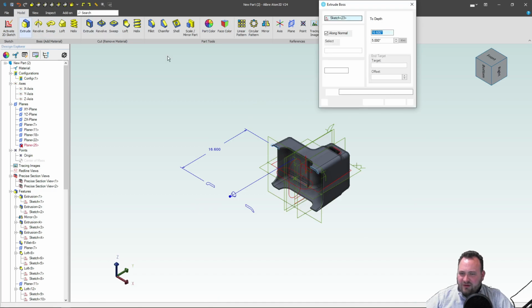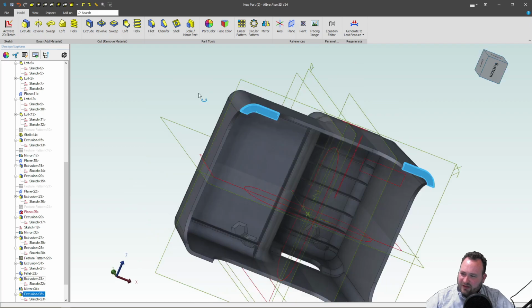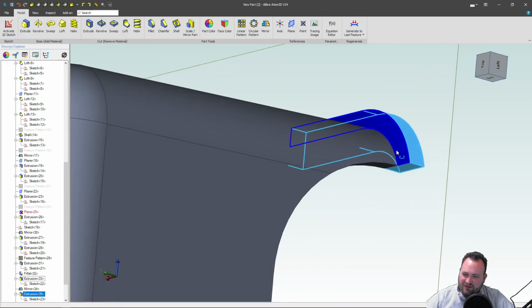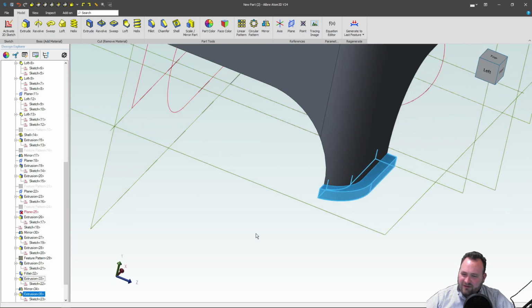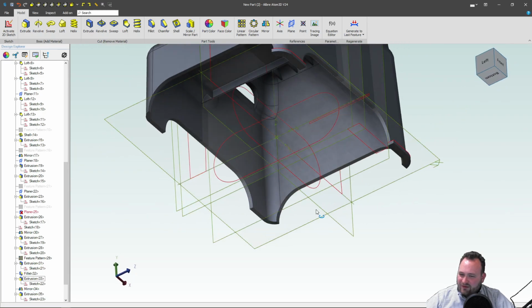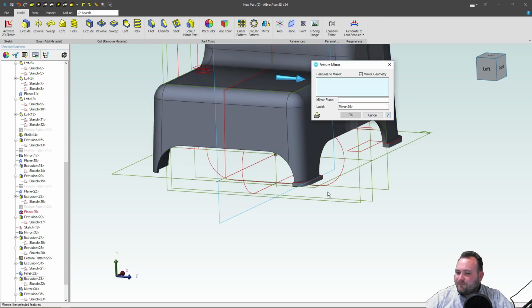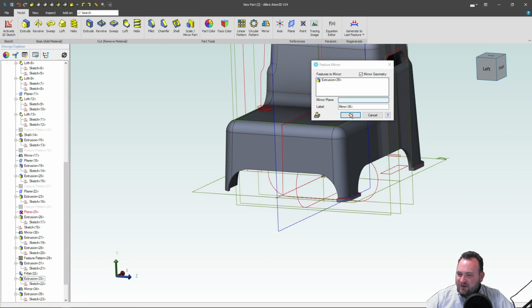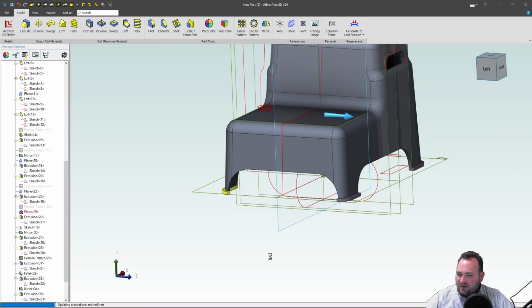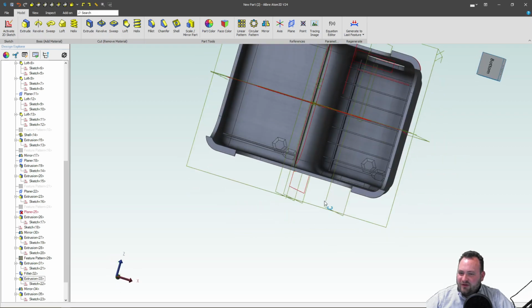We'll extrude 0.2. And there we have kind of a relatively consistent thickness there. Feel free to add fillets because that would be important. You know, sharp edges and injection molding isn't really that great. We'll go with mirror, and we'll mirror our extrusion across this plane. So we're rebuilding pretty good.